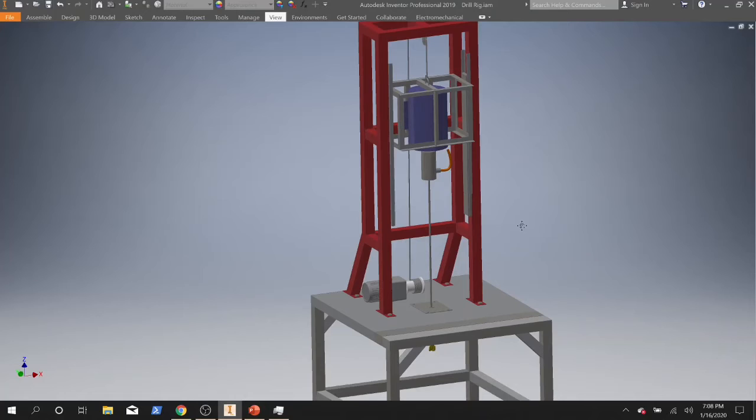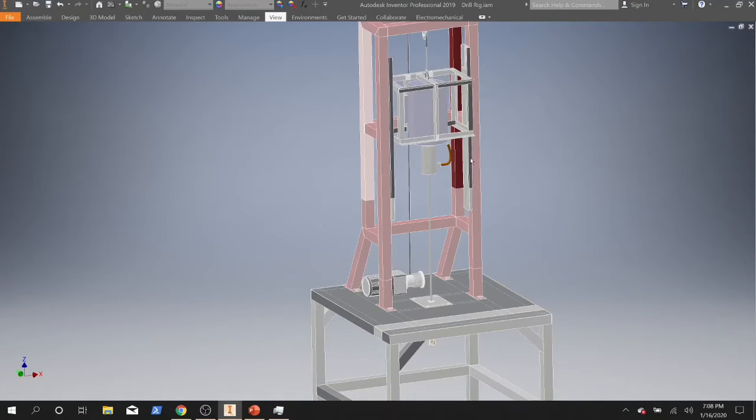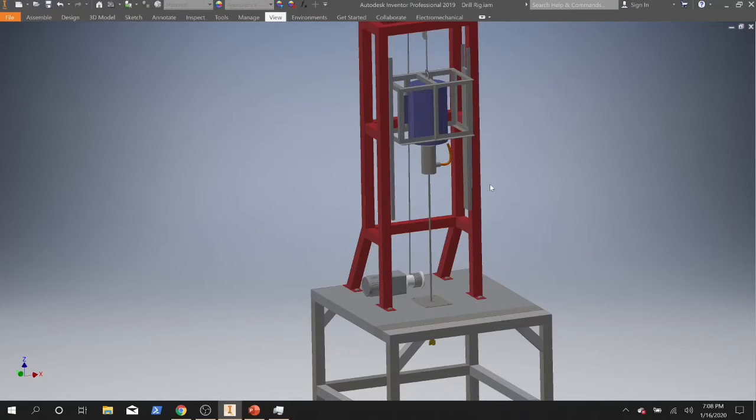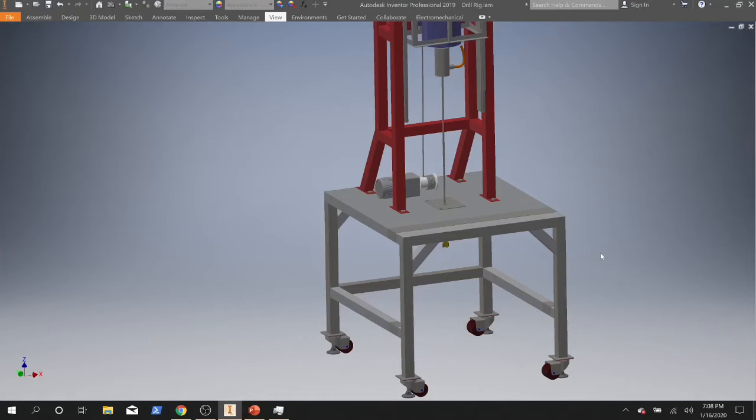The drawdown motor located on the drill floor governs the vertical movement of the motor and housing via a series of pulleys. The motor housing is attached to linear rails that guide the movement and allow for more than 30-inch stroke length while also ensuring the center of gravity is directed over the bed. The drilling floor consists of plexiglass to allow for both visibility and protection, and a mock rotary table to provide support for the drill string at the drill floor.